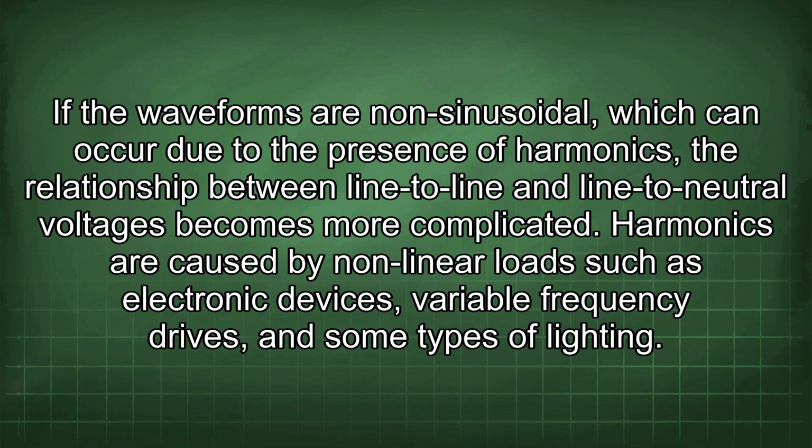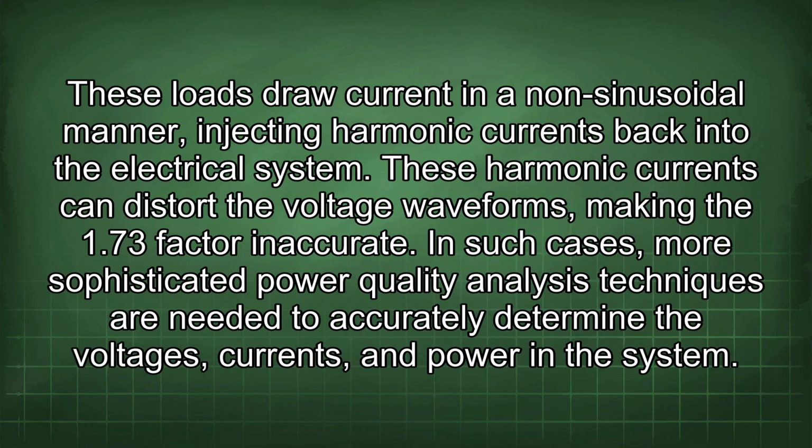Harmonics are caused by nonlinear loads such as electronic devices, variable frequency drives, and some types of lighting. These loads draw current in a non-sinusoidal manner, injecting harmonic currents back into the electrical system. These harmonic currents can distort the voltage waveforms, making the 1.73 factor inaccurate. In such cases, more sophisticated power quality analysis techniques are needed to accurately determine the voltages, currents, and power in